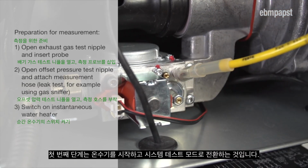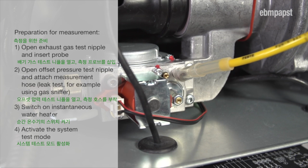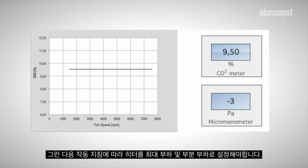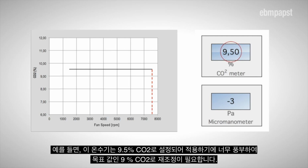The first step is to start up the water heater and switch to the system test mode. The heater then has to be set at full load and part load in accordance with the operating instructions. Start by switching to full load and checking the CO2 value. For example, this water heater is set to 9.5% CO2, which is too rich for the application and needs to be readjusted to the target value of 9% CO2.